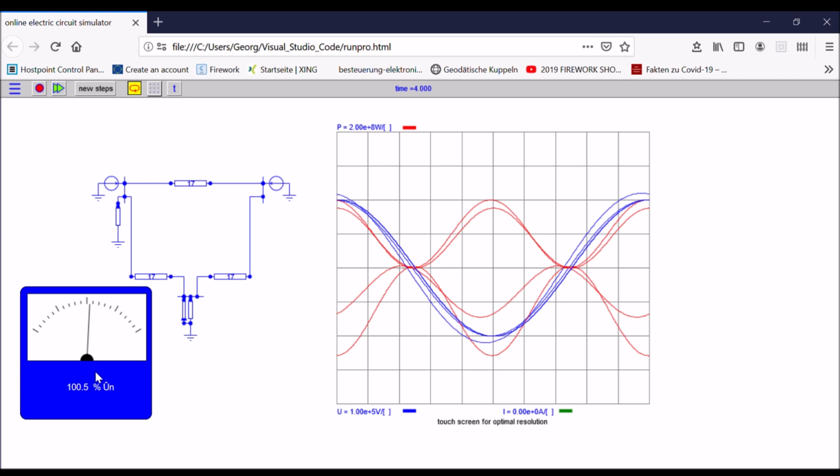And of the nominal voltage. But the problem is that now at this point I have a too high voltage. So I'm far above nominal here, and that would not be allowed. So the other option I have is that I compensate the reactive power at this point, and I do that by introducing a capacitor. Let's see how this is done.